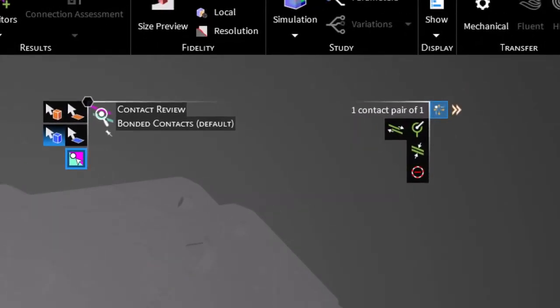Moving on, we have several options to choose from here. We can modify the contact to be a sliding contact which has additional modeling settings. We can change to a joint contact, but note that the contact pair must consist of collinear cylindrical faces or coincident spherical faces. Otherwise, the contact will default to fixed. We can change to bonded, which won't do anything to the contact since they are already bonded by default, but you will be able to group them as bonded contacts separately. Finally, you can change to the prevented contacts to ignore them.